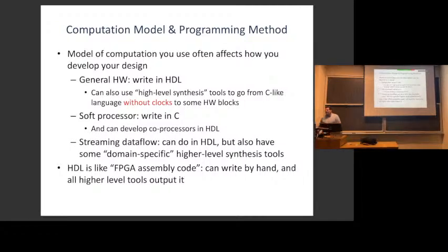So that's the software running on the processor. Yeah, so that's the software running on the soft processor. Usually you write your own software. You could make your own soft processor, and you do that for something called overlays, where you make very unusual soft processors. But if you're making a very conventional one, where I just want to run normal C programs, usually you use Nios or RISC-V or MicroBlaze. You just get it from one of the vendors and they wrote the RTL, you compile it, and then you write C to run on top of it.